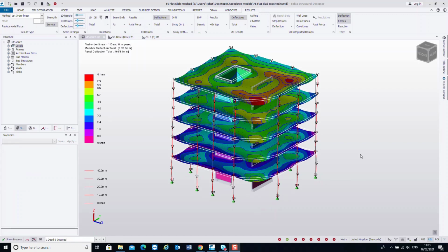Reducing the lateral displacement will reduce the force carried to the core wall systems, or for braced bays if we were looking at a model with bracing, leading to smaller moments and forces within those stability systems. If we intend for the stability systems to resist the lateral movement, this will result in incorrect reduced forces being used to design these stability systems.